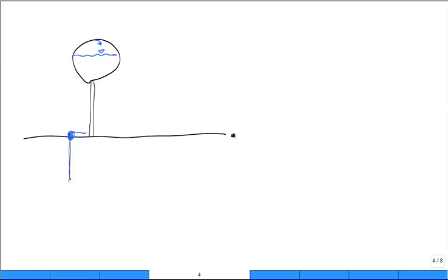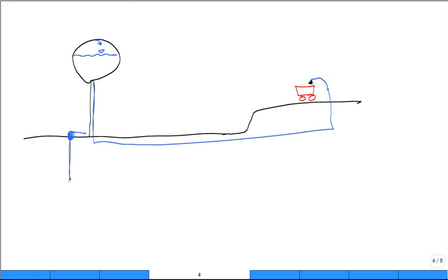Okay, the other one is the terrain is like this, then it goes like this, then it goes like this, and, well, they don't go that high, but let's say it's up like this. And you have a truck up here, and he's got a water tank on it, and he's going to be in the pipe distribution system. He's got a fire hydrant here, and do you ever notice how they fill those water trucks? They have a loose little flapper at the top that does not go into the water tank. They do not put something into the water tank on the truck. And they have a big sign on it that says, non-potable. Don't put it in your pot.